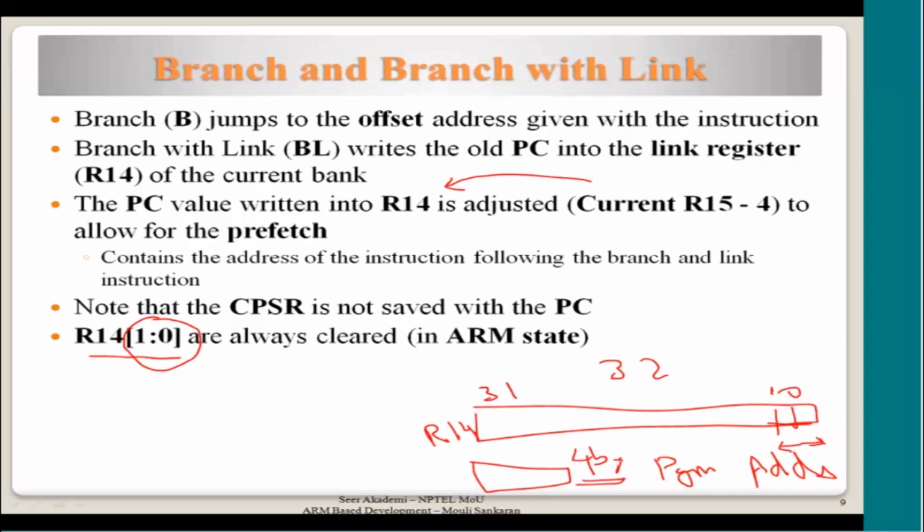That means if the address 1000, our favorite 1000, is the first instruction, the next instruction will be at 1004 only. Can there be any instruction between these two addresses? Can it be 1001, 2 or 3? It cannot be. You agree? You jump from 1000 to 4, from 4 to 8, so the addresses keep incrementing by 4.